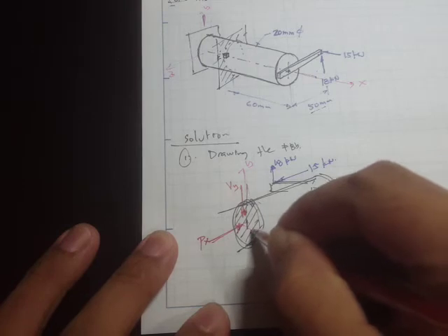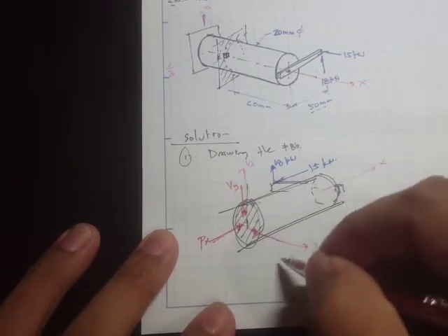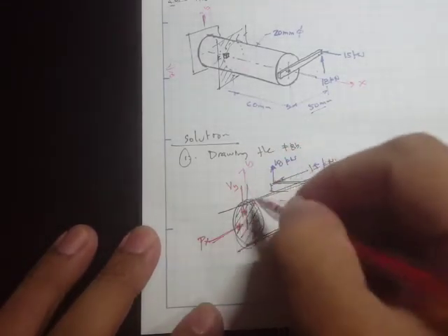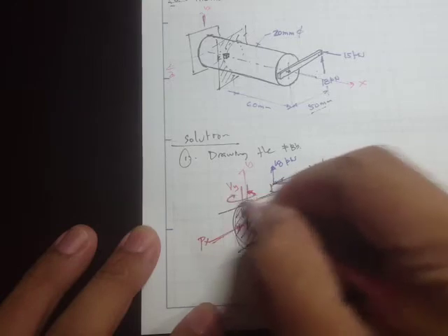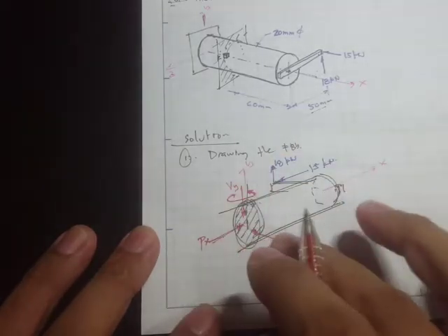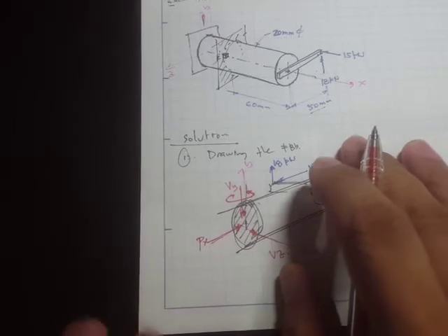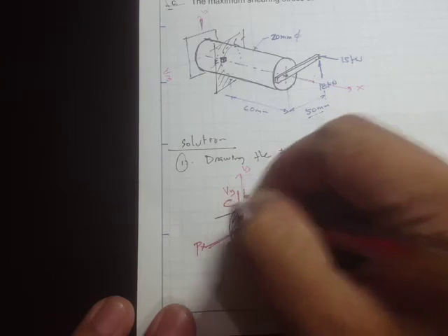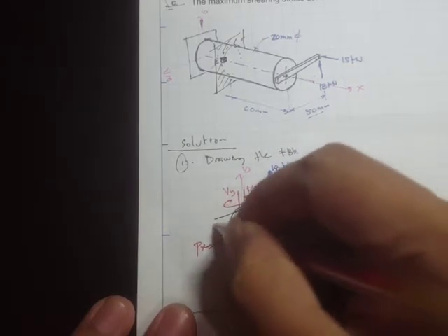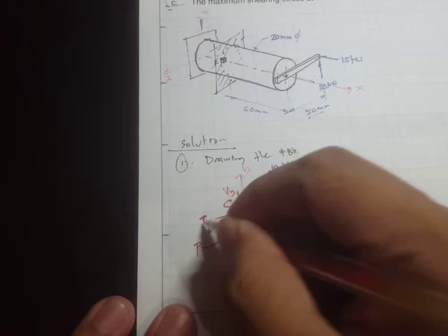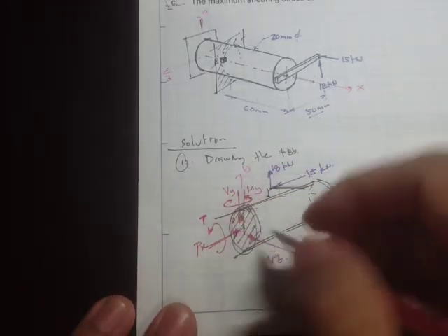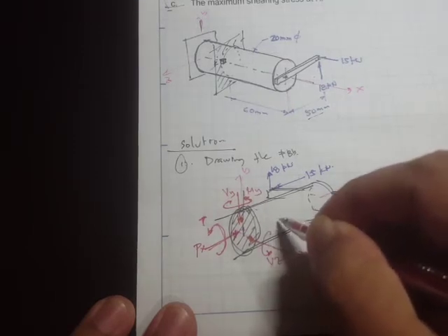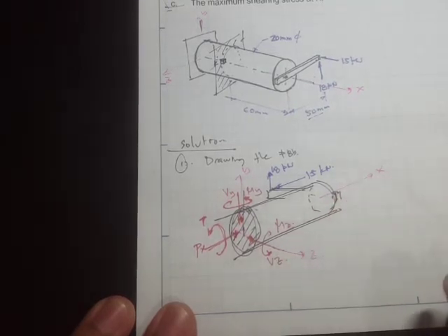And right here we have also forces, and let's say this is V Z. And if we have forces, then we also have moments right here. So the direction is just random. If we compute and it happens that it's negative, then it means that it's the other direction. So this is moment along the y, and this is torsion. Okay, so the moment along the x is actually torsion. And right here we have the moment along the z-axis.